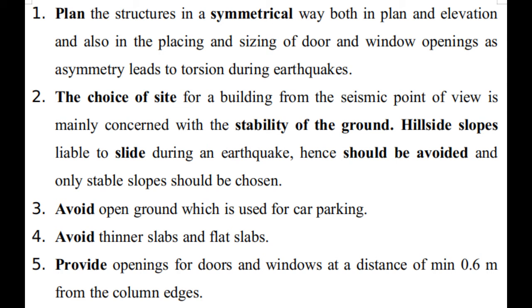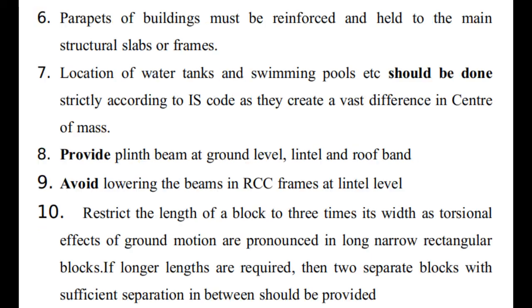Point number 3, avoid open ground which is used for car parking. Point number 4, avoid thinner slab and flat slab. Point number 5, provide openings for the doors and the windows at a distance of minimum 0.6 meter from the column edges. Point number 6, parapets of the buildings must be reinforced and held to the main structural slabs or frames.